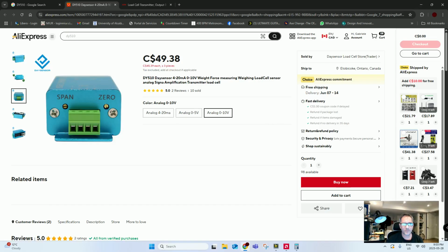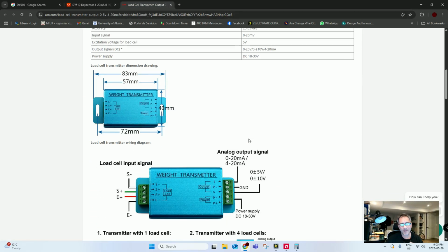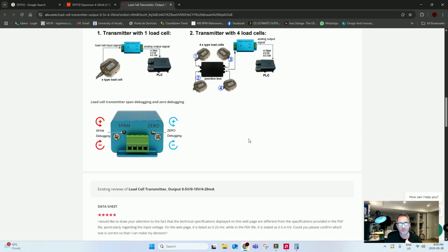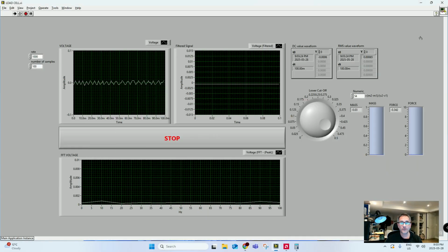It's a very affordable price, especially if you're planning to make an application like the one that I'm using right now. Obviously, by reading the spec and by doing the calibration with two simple masses, you get the correct signal. Now let's rotate the screws clockwise to zero, and it's right here. I don't move the load cell because it's very sensitive. As soon as you move it, the signal changes. Okay, looks okay, perfect.